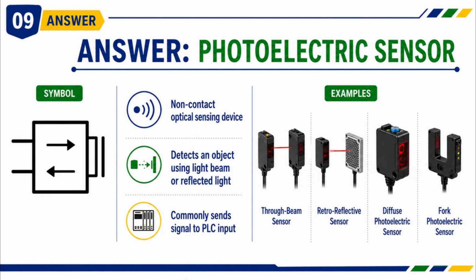A photoelectric sensor is a non-contact optical sensing device. It detects an object by using a light beam or reflected light. These sensors are commonly used to send a signal to a PLC input. Common types include through beam, retroreflective, diffuse photoelectric, and forked photoelectric sensors.